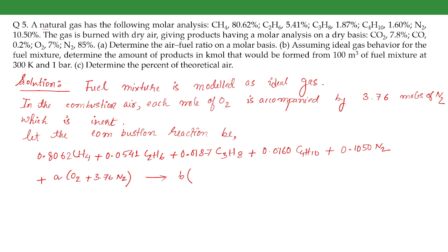Please try to understand the difference between the molar analysis on a dry basis and dry air. In dry air there will be no moisture present, but when the analysis is done on a dry basis, we are not considering the moisture, but the moisture will actually be present. That has to be included separately.